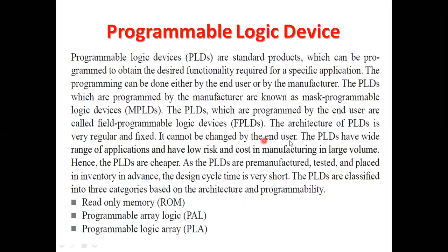It cannot be changed by the end user. The PLDs have a wide range of applications and have low risk and low cost in manufacturing in large volume. Hence, the PLDs are cheaper, as the PLDs are pre-manufactured, tested and placed in inventory in advance. The design cycle time is very short.